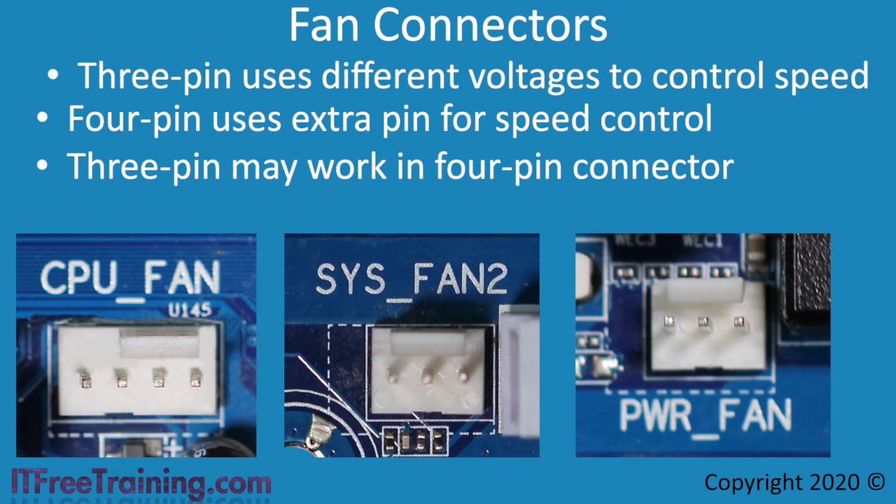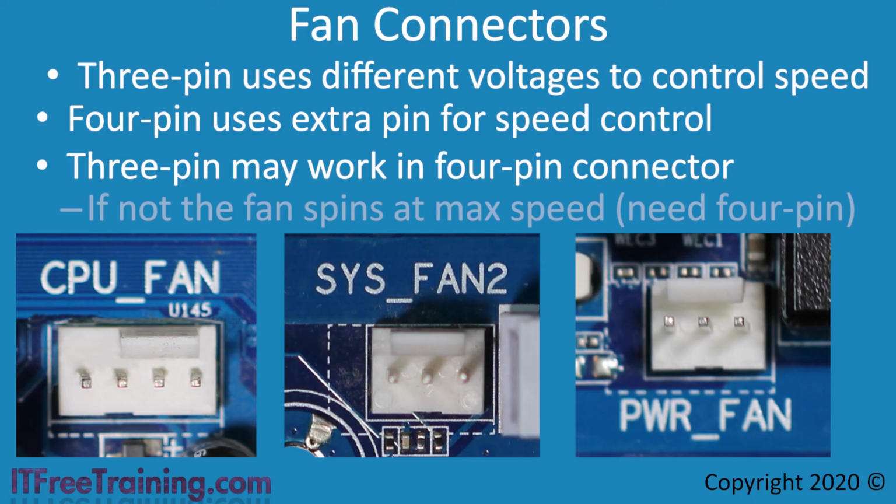On some devices, like video cards, if you plug a 3-pin fan into a 4-pin connector, it will not work. You will know this does not work because the fan will spin at full speed the whole time. If this occurs, replace the 3-pin fan with a 4-pin fan. On your motherboard, all the fan connectors may have the same type of connector and support 3 and 4-pin connectors. However, you should take care to plug the fan into the correct connector.